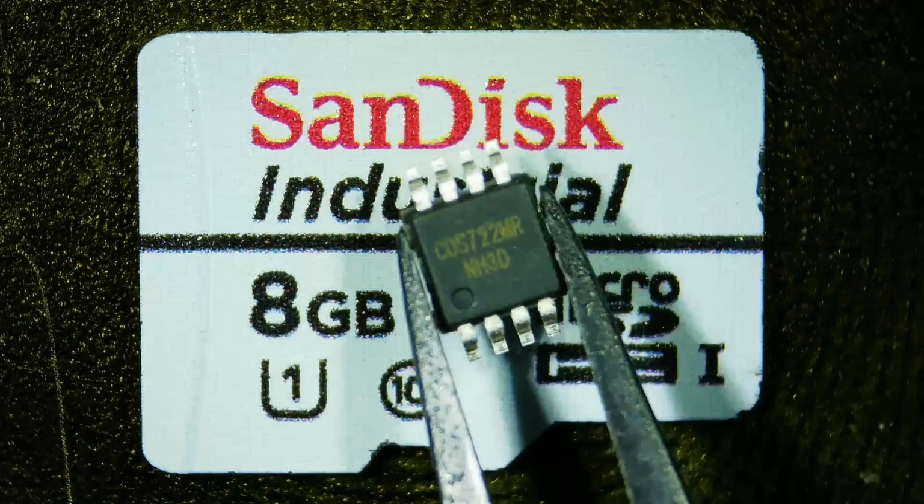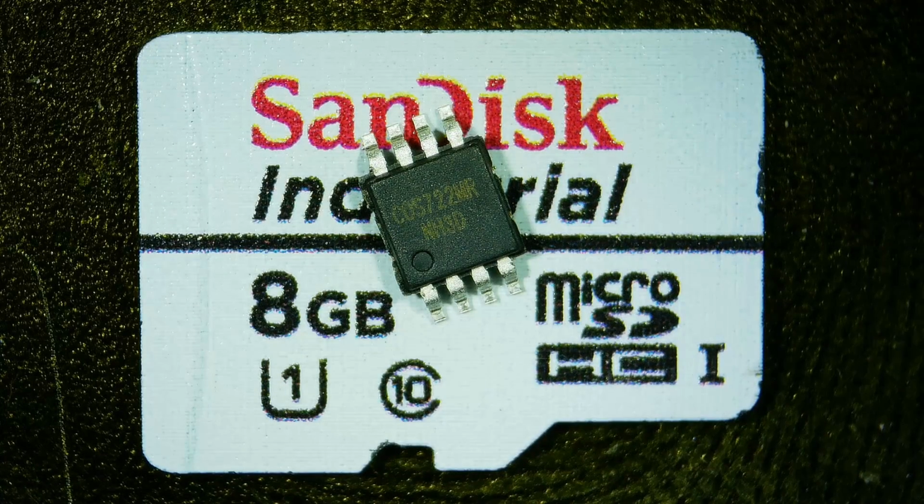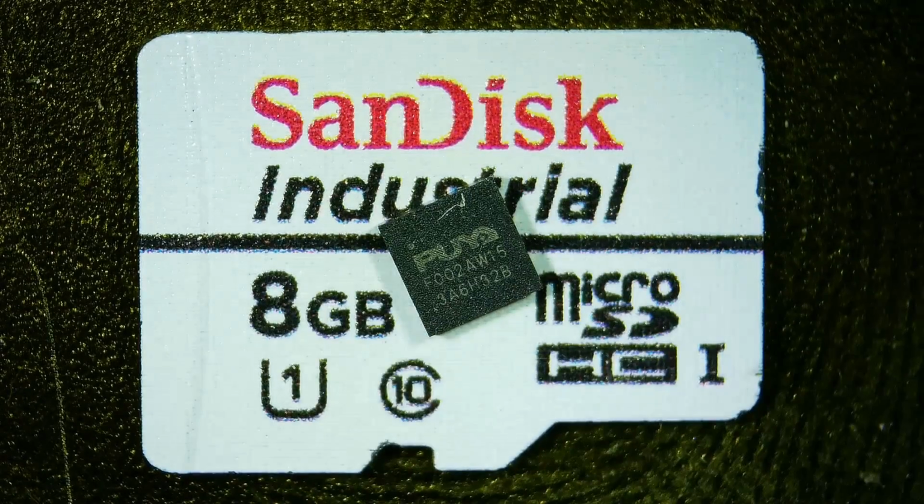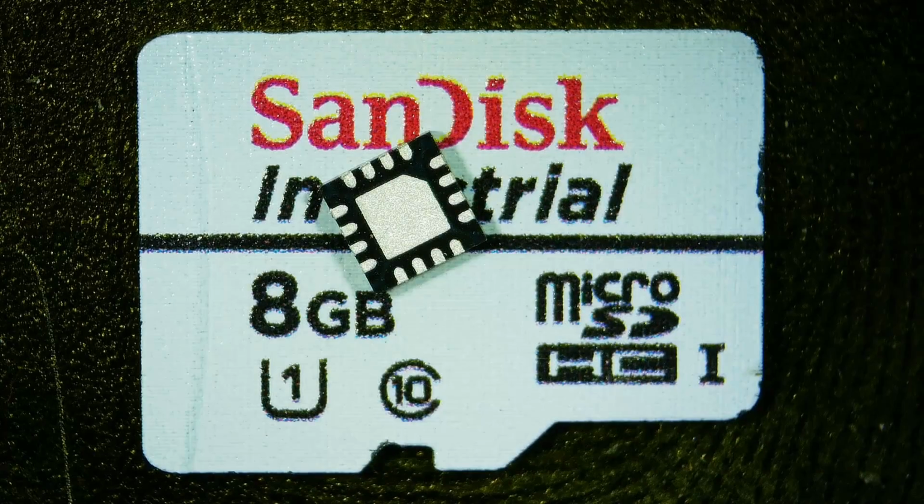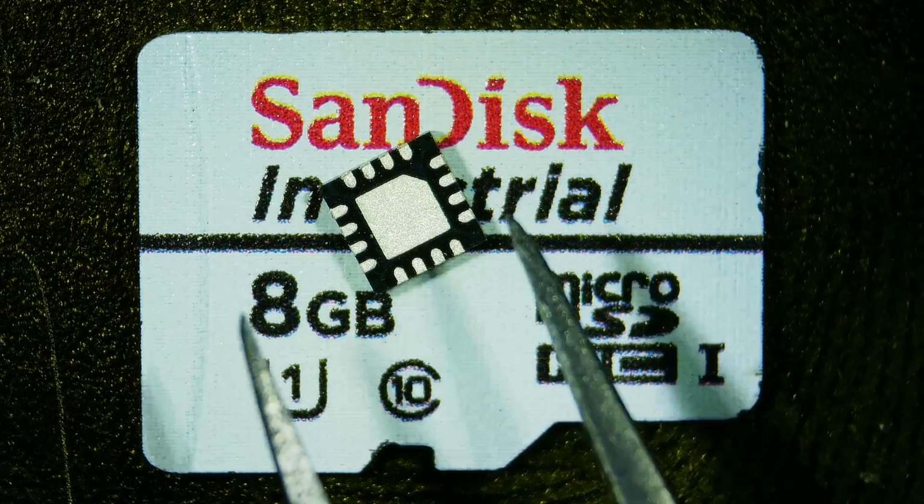For that amplification, I'm using a Cosine COS722 dual op-amp. By using a dual op-amp, I can put only one extra part on the PCB. Finally, the microcontroller I selected is the PY32F002 in a QFN16 package that is only 3 millimeters square. I ordered 500 of all these, and at that quantity, basically every part came out to 10 cents each. I also bought a bunch of passive components. These all came from reputable companies, and they actually ended up costing more than all of the active parts.